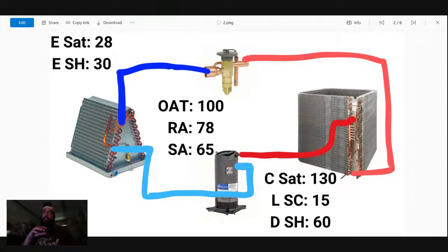In this particular case, yes, we gave it 2 revolutions, we give it 20 minutes. Our graphing on the app shows we're stable. And I'll say that, just by chance, two revolutions was the correct call. We're back up at about 40 degrees of saturation. That's going to bring us back down to about 10 degrees of superheat.